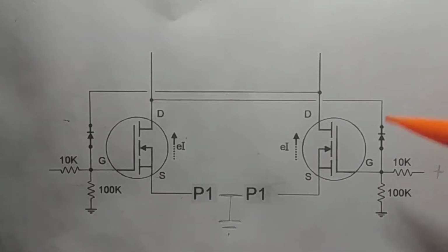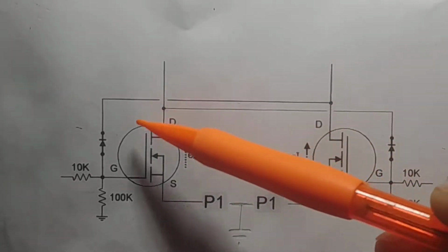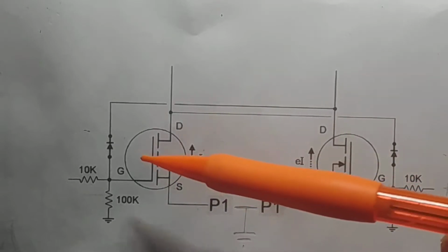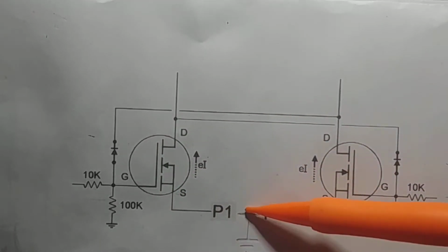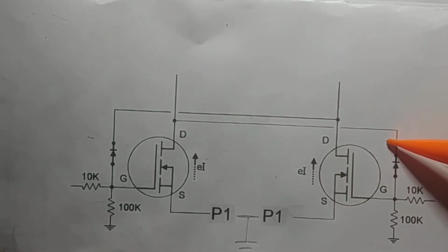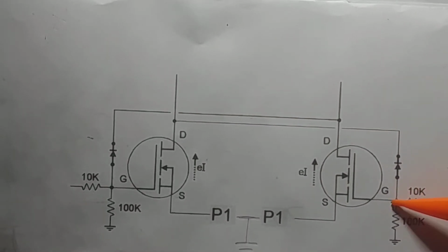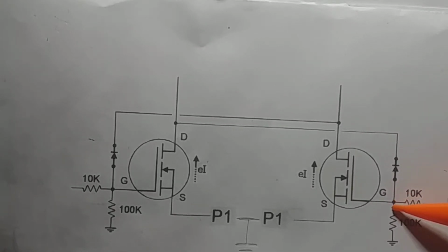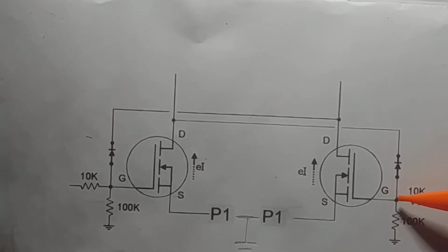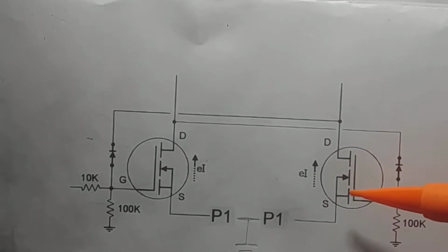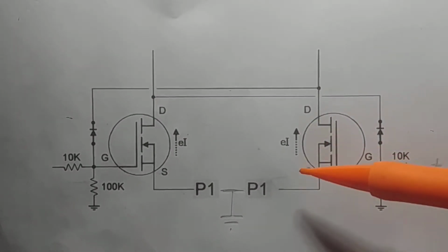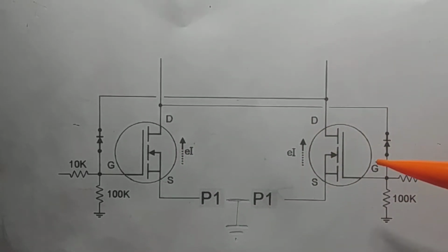When the gate comes on, these diodes are fed from the other side. So let's say this one's on. Current is flowing up through here. It will also go across to the other side through the diode and put a negative potential on the grid and shut it off. And that's what I want to do, is I want this one to shut this one off and this one here to shut that one off.